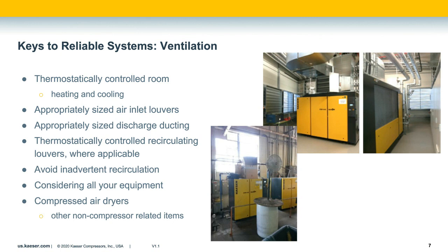Negative pressure in the room is going to make your compressor work harder. So for the amount of flow that you're putting out, your compression ratio is going to be increased, which means your power consumption is going to be increased and you're taxing all your equipment more. Not to mention that you don't have enough cooling air, so your operating temperatures are going to continue to elevate and your compressor is going to shut down, which we want to avoid.